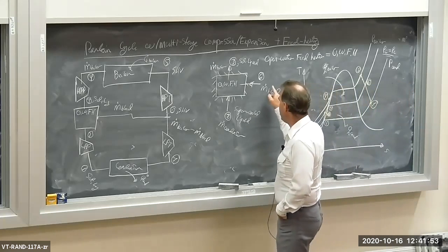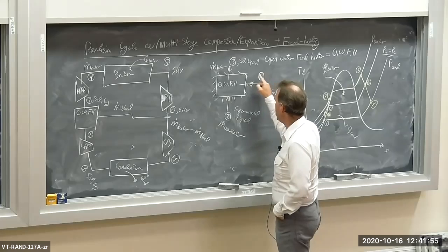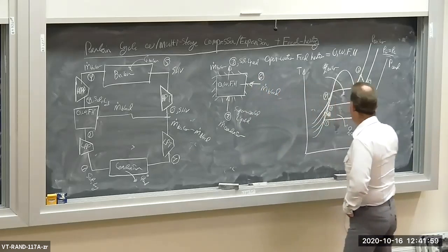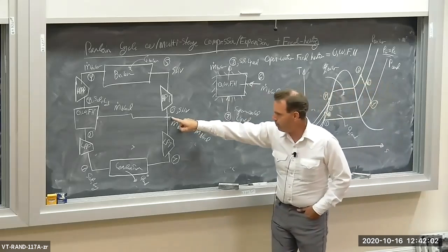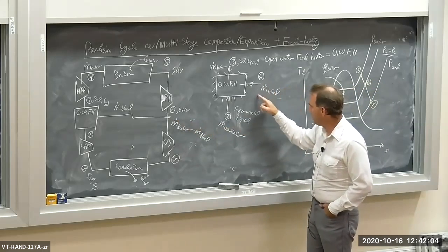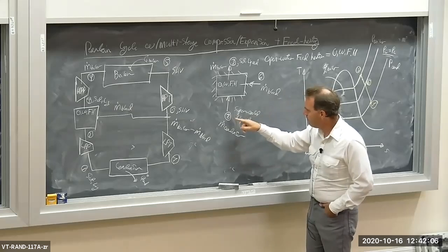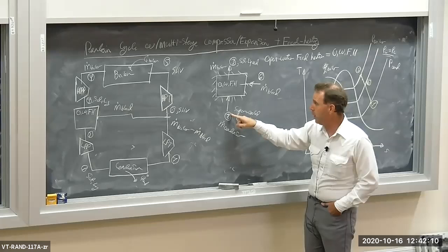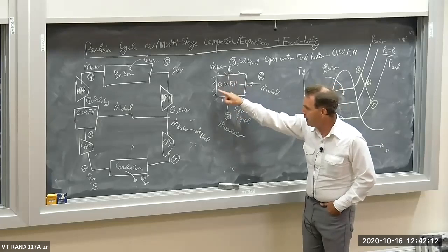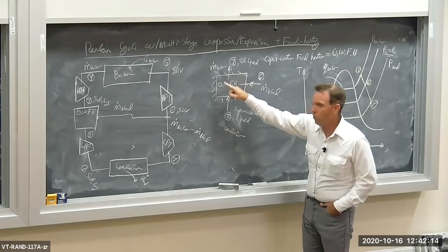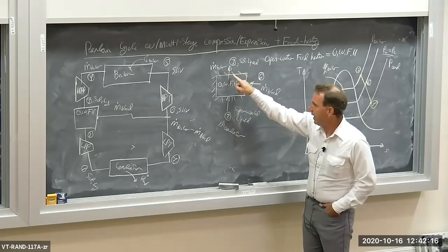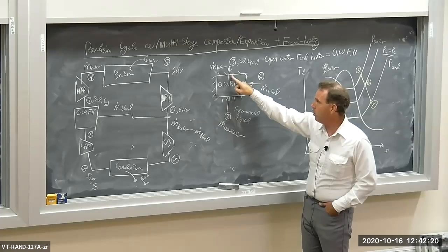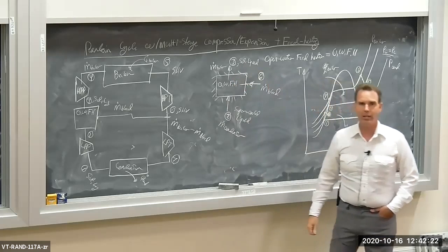So we're bleeding off a certain amount of H2O from the exit of the high pressure turbine. We're going to mix it with supercooled liquid, which comes from the low pressure pump outlet. We're going to mix it isobarically in this open water feed heater, and that's going to push us up to state 3. It's going to heat up the H2O at state 3 to a saturated liquid.